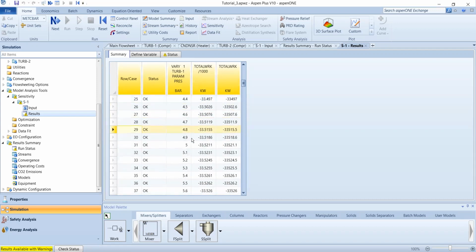And at what pressure do I get the maximum work? Basically the highest negative. So let me have a look here. So it seems to be increasing. I'm just looking at this table. So it's increasing 5.2, and then it's dropping to 5.1 again. So it's somewhere in this region, 5.25. Yeah, so it seems that the maximum discharge pressure of 5.7 bars gives me the maximum amount of work. Let me just have a look here at the bottom. It's minus 32. I'm not interested in this.